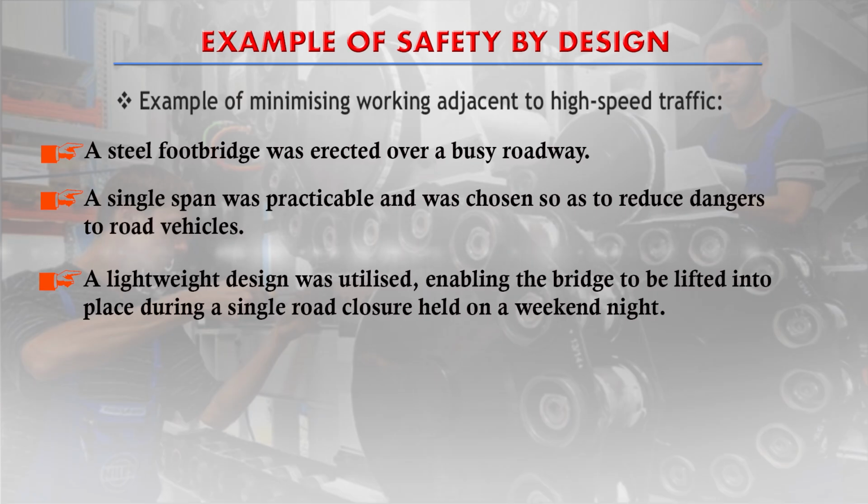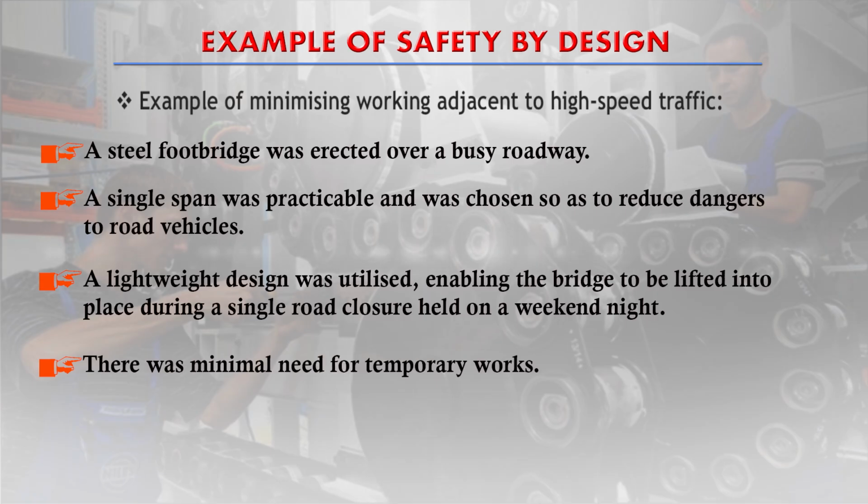Or else, suppose this is not a lightweight design, and it is not a single span, then the road closure might have been for several weeks, and during these several weeks people will be adopting shortcuts, and then it may lead to injury. There was minimal need for temporary works. Temporary works is always required for any such erections, but at the same time they are not as safe as the permanent work. Therefore, by this design, the risk has been minimized.